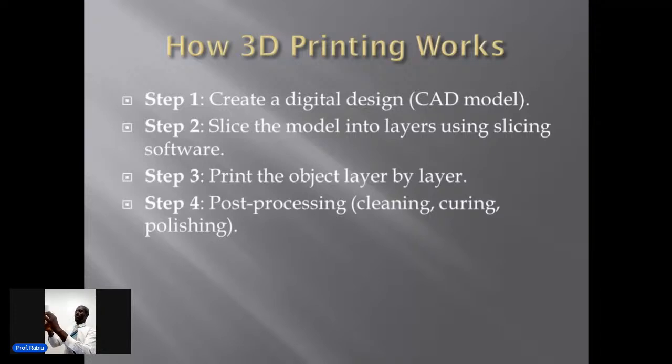Because this is the base. I can still remove the base. It sticks to the tray. But once the tray is cold, after some time, this is movable easily. That's the reason for creating the base. It holds it when it's hot. Once it's completed, it will ask you to remove your model. By that time, when you touch the tray, it's movable. But before that, you'll be struggling to remove it, and you may even spoil it because at that time it's a little bit hot. Right?